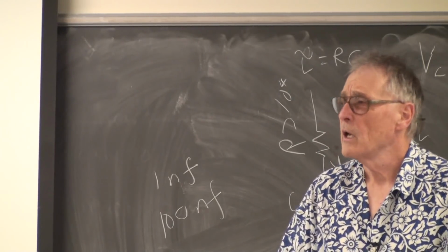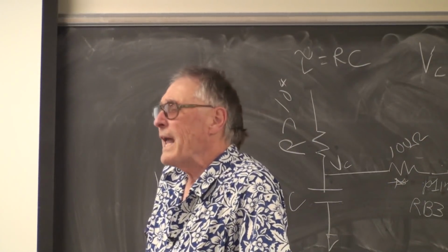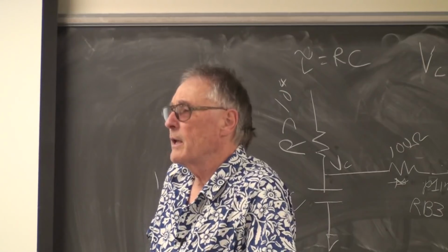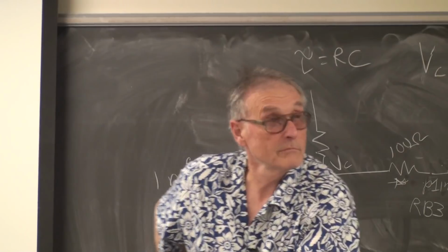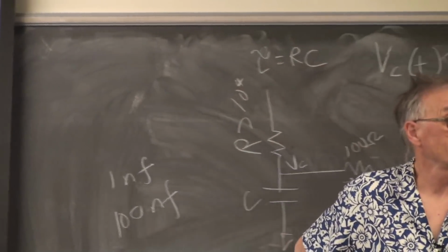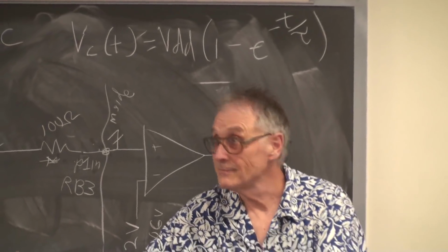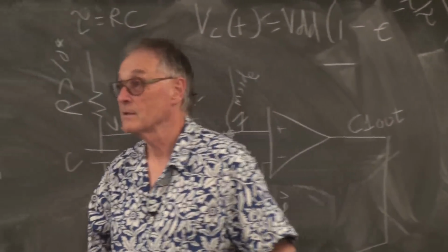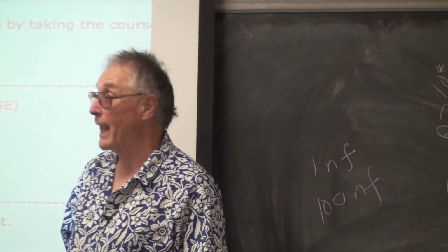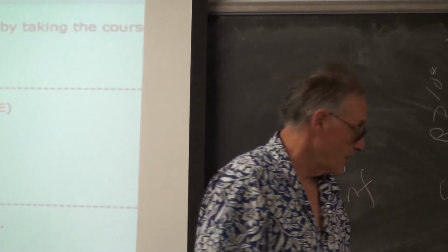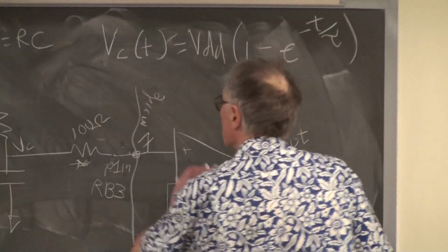So, CMOS inputs have infinite input impedance. What happens if you leave a port pin as an input unconnected? What is its voltage value? Anyone? Yes? Is it floating? It is floating, which means you don't know. It can be any value. Now, could it be 1,000 volts? Mercifully not, because